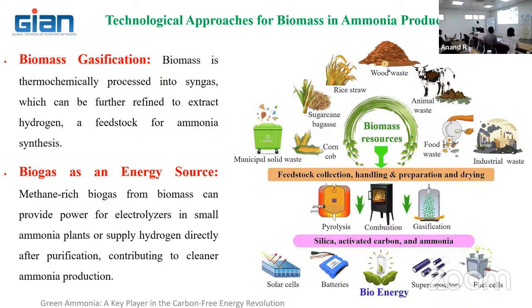Here, in combustion, we will get only the products of combustion in the form of gas, whereas in gasification, you are going to get solid, liquid, and gas. Here the gas is predominant. Whereas in pyrolysis, you are also getting three products, solid, liquid, and gas, but here the liquid is predominant. So you are converting the solid material into gas completely. Maybe 10 to 15% is solid residue. The remaining 85% is going to be converted into gas. In that 85% gas, something is going to be condensed, something not going to be condensed. The condensed gas is nothing but liquid. So the product of the pyrolysis reactor is maximum going to be liquid.